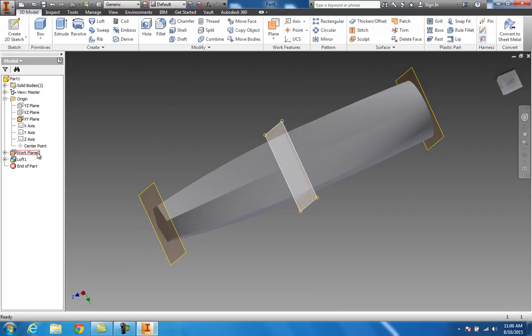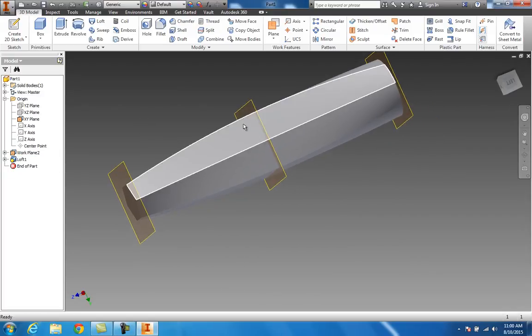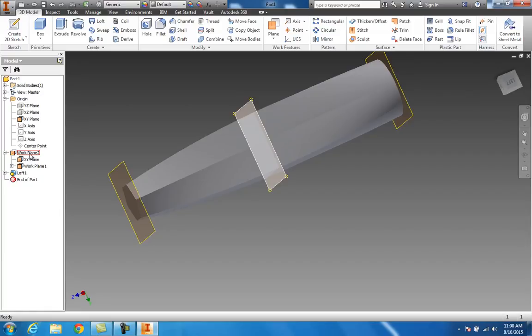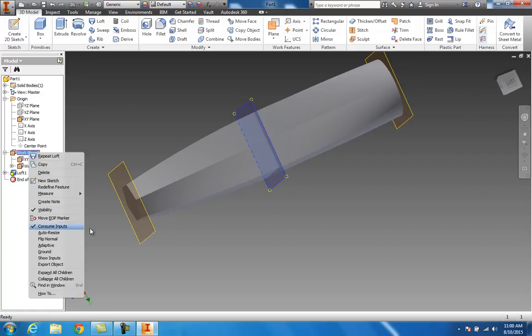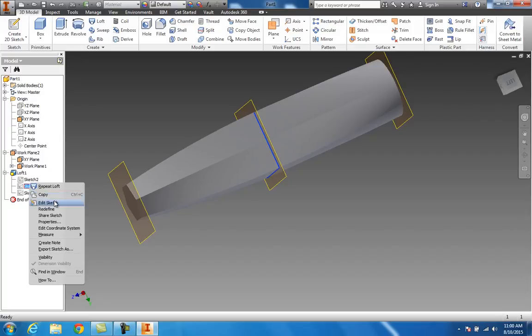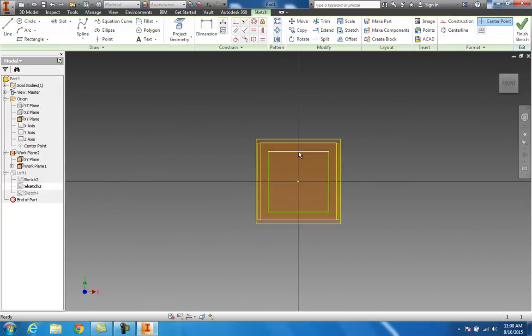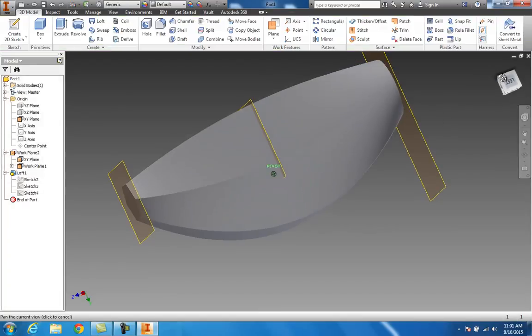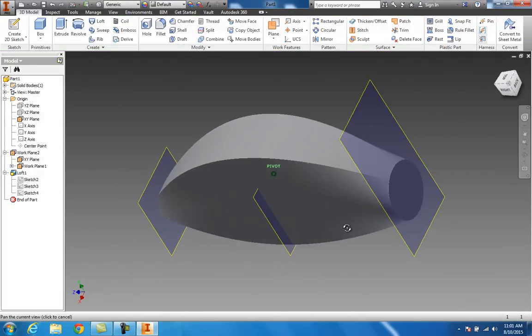Now again, you can change things. You can actually move and make stuff curve. Go in here in this work plane right there. Let's say I want to edit this sketch right there. Watch what I can do. I can move it a little bit. I can just change it dimension wise, or I can actually move it out of its spot. You can see how it automatically adjusts to it. It's really, really cool. That's your loft.